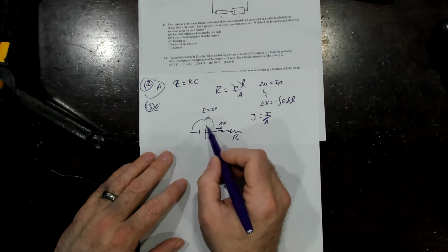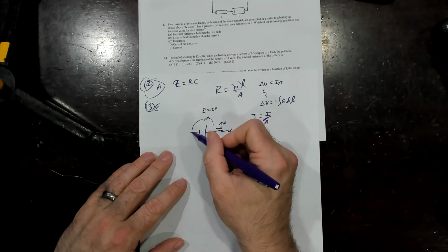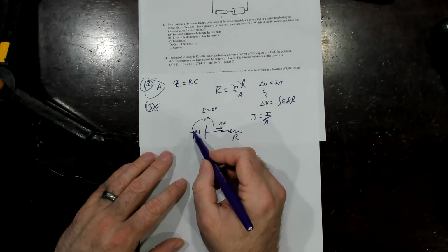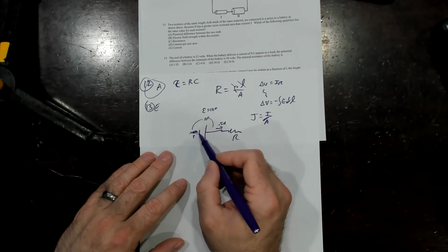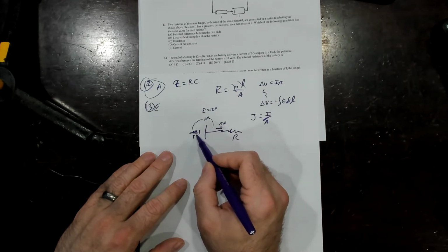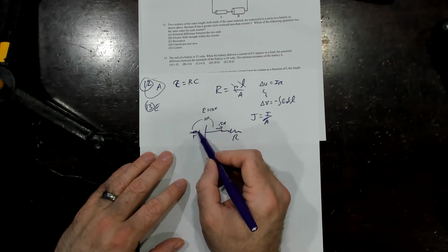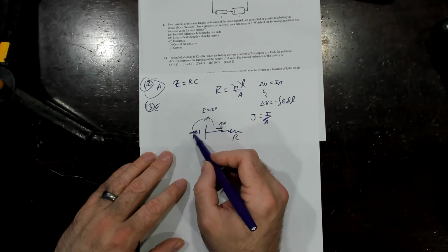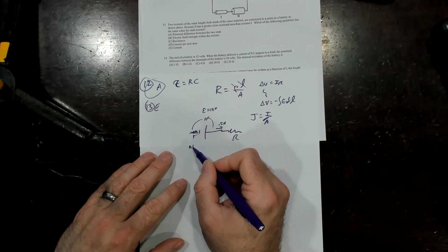Why? Because there's internal resistance in the battery, built in, that you can't get around, and I'm going to burn off some energy in that battery. So I'm going to go down some voltage in the interior of this guy, and up the 12, to get this overall change of 10. So I'm going to go down 2 volts going through this.